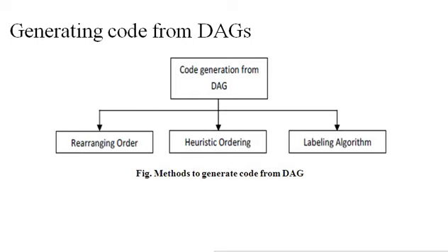Then your improved code will be move C comma R0, add D comma R0, move E comma R1, sub R0 comma R1, move A comma R0, add B comma R0, sub R1 comma R0 and move R0 comma T4.